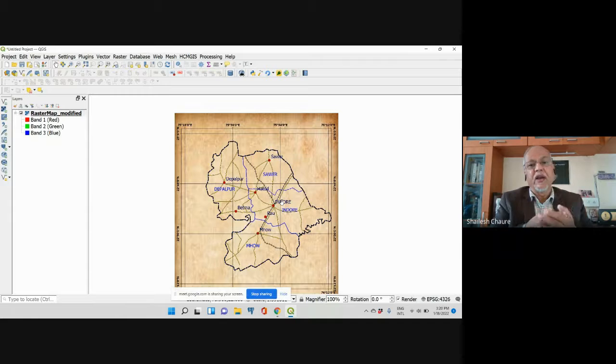And while creating the shapefile, you have to decide well in advance what kind of features you want to store in that. Suppose I want to create the point data. I may call it location.shp. So in that location file, while creation of that file, I have to define that this is a point file. The type of features in the file will be point. So you will not be able to add lines to that. You will not be able to add polygons to that. Okay. So feature wise, we will create the files, and each file will represent a single layer over here.